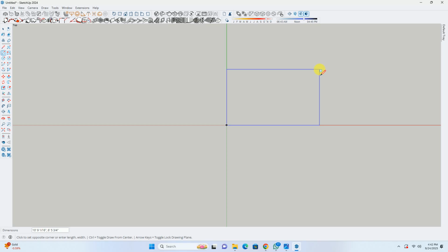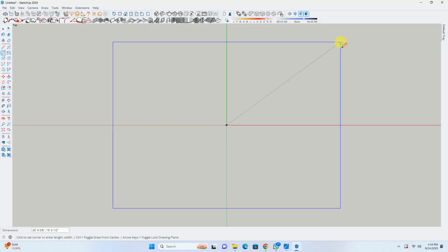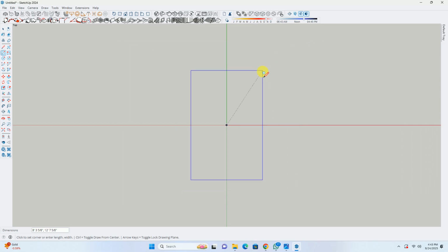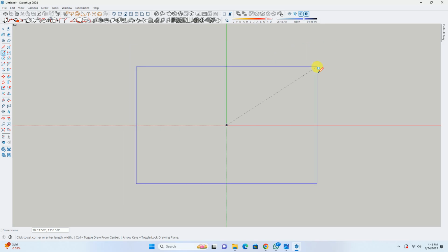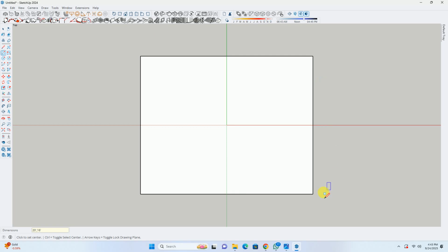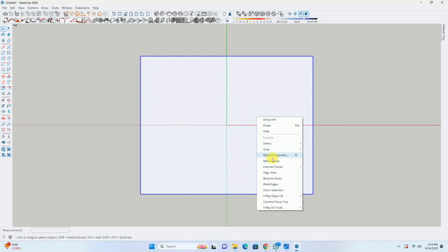Okay. What we can do is we can press the control key, and we can press control. Then the rectangle will start constructing from the point that we have given as the first point of the rectangle. That point will be considered as a center point, and a rectangle will be formed from that particular center point only. Now we'll specify the dimension. We have taken into account 20 feet by 16 feet of room size. Okay, so we have created a rectangle of 20 feet by 16 feet. If you want, you can write it down also.